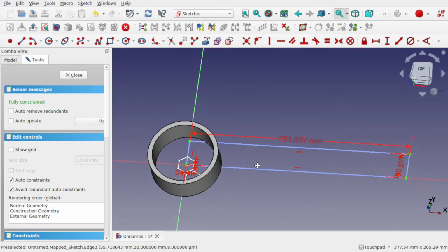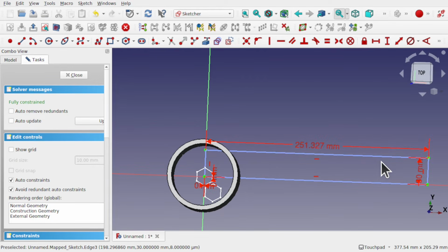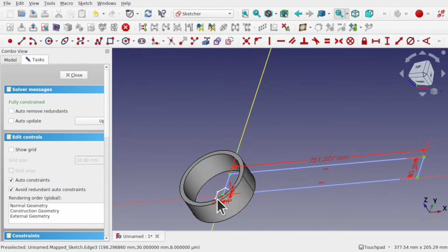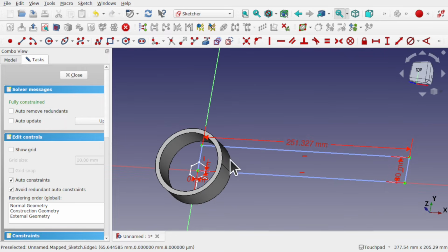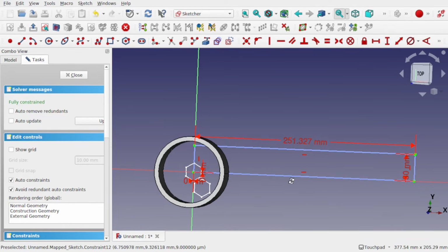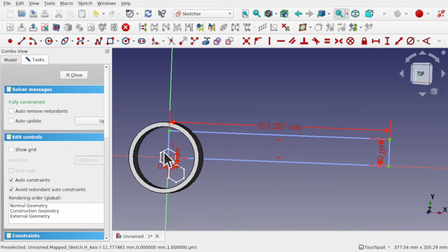So this will only work if we take a simple object like a tube and unwrap it. Anything like B-splines or tapered lofts, etc., then we get a different layout of the sketch, and we have to actually create the sketch and figure out the circumference of the object and recreate this sketch in here. It will appear as a small sketch basically at this point, but this is unwrapped fine. So this is the circumference of this circle.